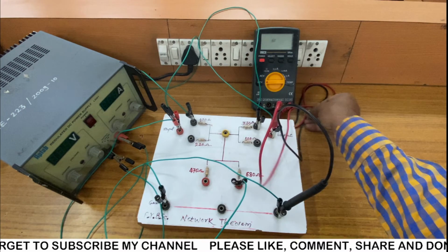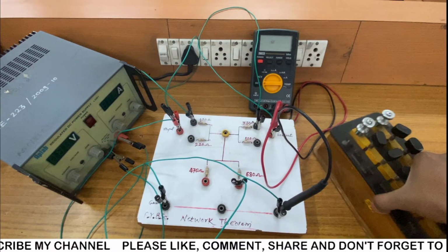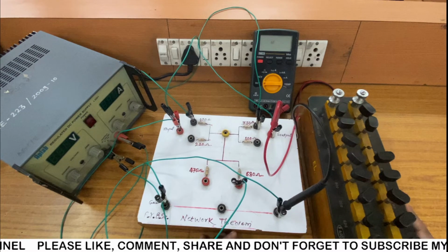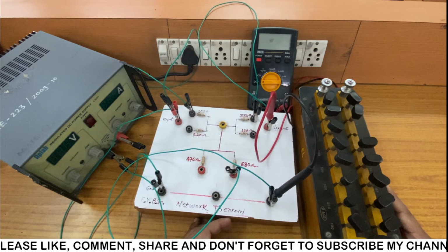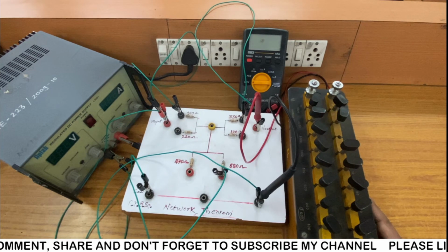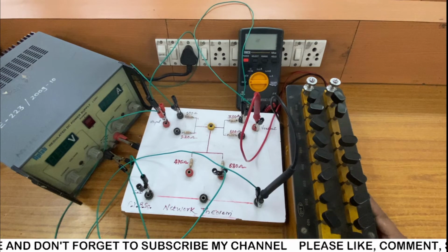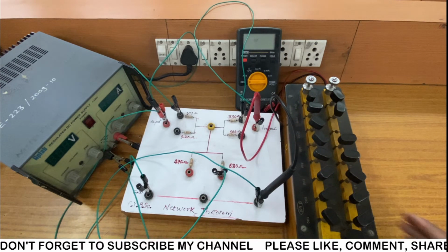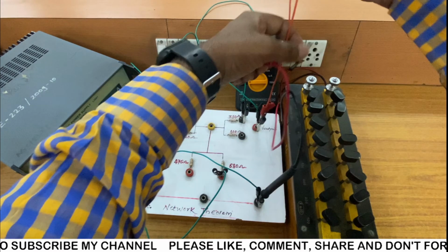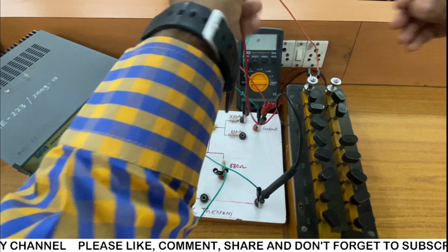So what we are going to do, we are going to have a load resistance. So this is a resistance box. I'm going to connect the resistance box to the V out and ground pin. So you can see the V out pin should be connected to the resistance box's first terminal and the ground pin should be connected to the resistance box's next terminal. For that purpose, I am going to remove the multimeter's positive.